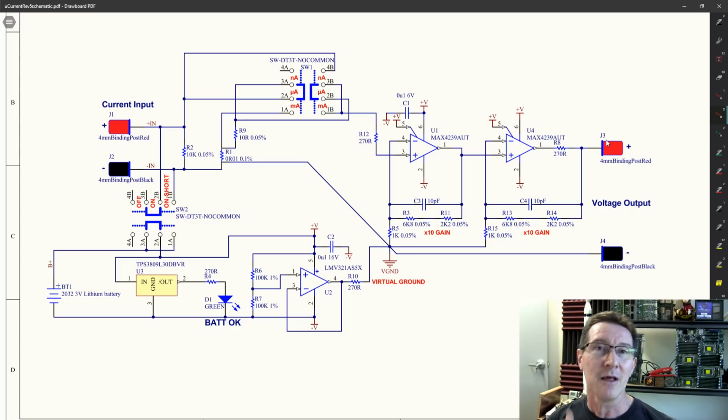So you want the offset voltage to be basically the least significant digit of your measurement device. So we're targeting that nominal 0.1 microvolts offset voltage. So we're looking for anything better than that. If there's nothing better than that on the market, maybe we can get something that's the same, but it might be cheaper, for example. So there might be benefits, or it might be higher bandwidth. Because I didn't finish my thought before, there were two design requirements. One is the offset voltage, two is the bandwidth. And on this one, we want to increase the bandwidth. What is the bandwidth in the microcurrent? I forget, it's like 300 kilohertz or something like that.